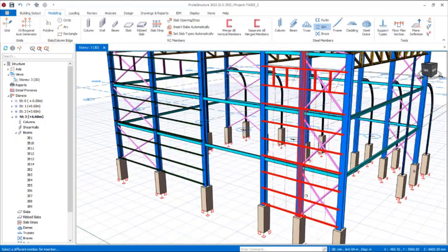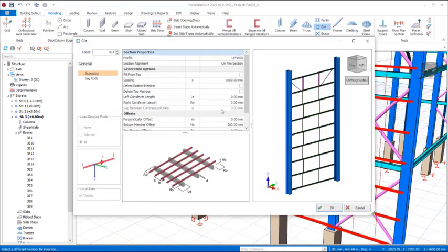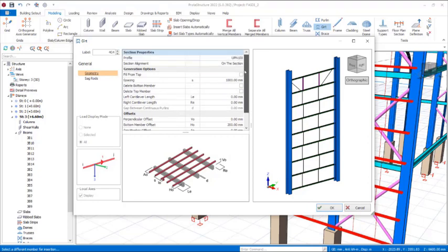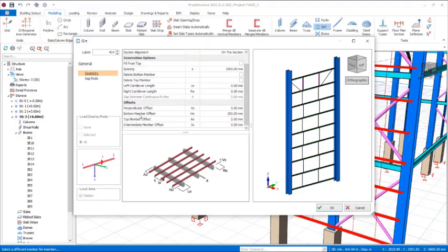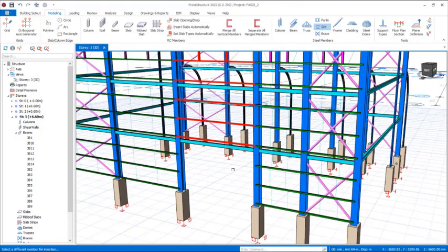Okay, so for this and this, we are going to be having this place as our entrance. Okay, this is one of the entrances into this warehouse. So we place a gate from this point to this point. I'll show you how to adjust that, and then come straight away to where you have some offset here. You can see bottom member offset is 200. So this place now you change it to 3200, just like this. So click on these provisions to have it shifted. You can see it's been shifted to this S10. Click on the OK option, so you can have this place open, okay, for the entrance door.